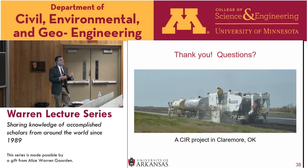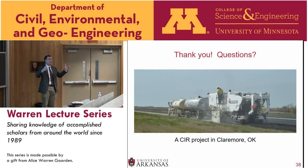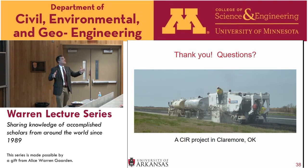So hot in place recycling, it's really fascinating to see because there are 4 to 5 heaters. So they're like giant hair dryers that are 12 feet wide and about 20 feet long, and they pass very slowly over the pavement, and it heats the pavement surface. After that pavement surface has been heating, 1 to 3 inches gets milled up, usually rejuvenating agents placed in there, and then it's laid behind them.